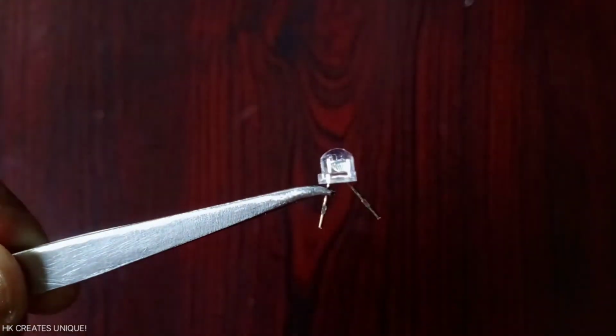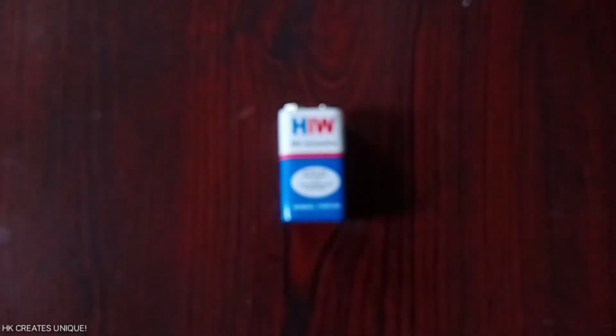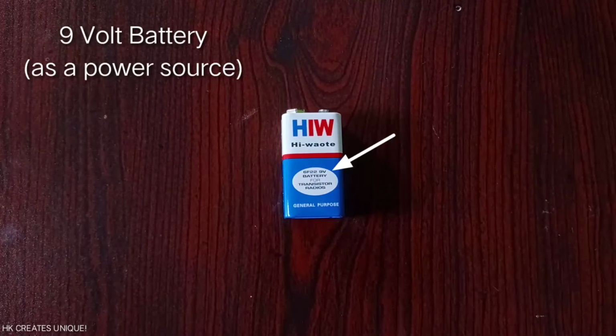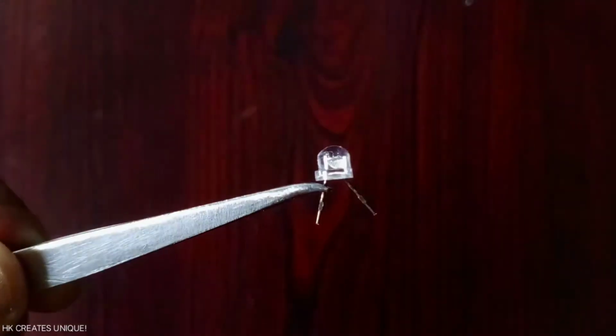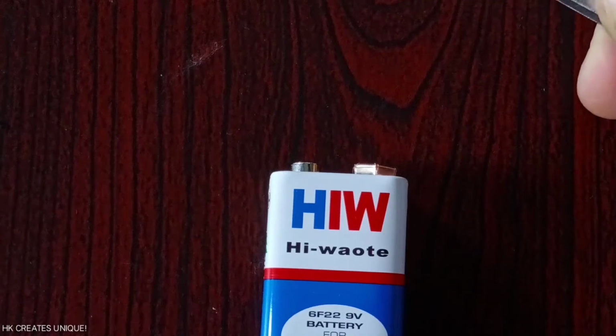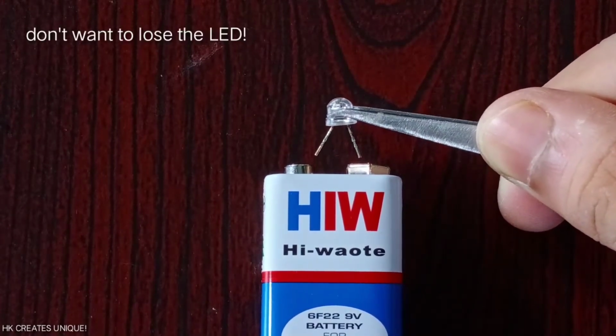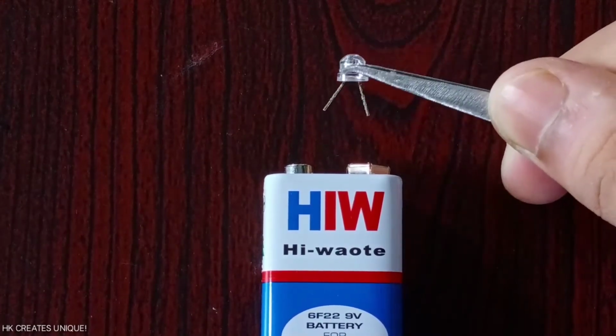I want to light up this LED. The only power source I have is a 9-volt battery. Unfortunately, the maximum voltage this LED can handle is around 3 volts. So if I connect the 3-volt LED directly to the 9-volt battery, it will get damaged.